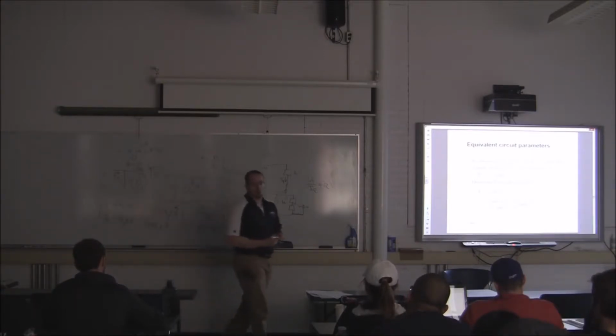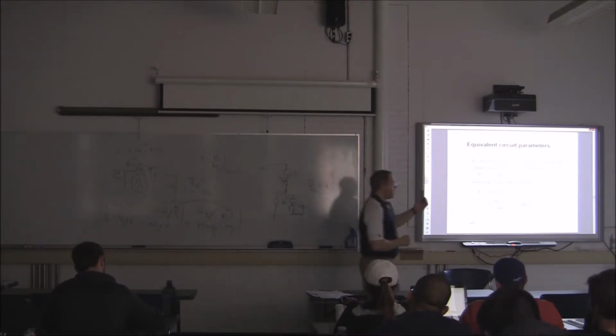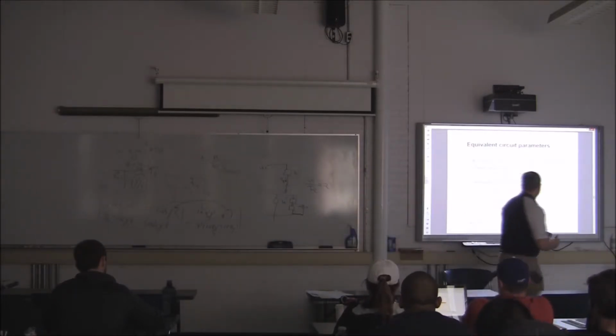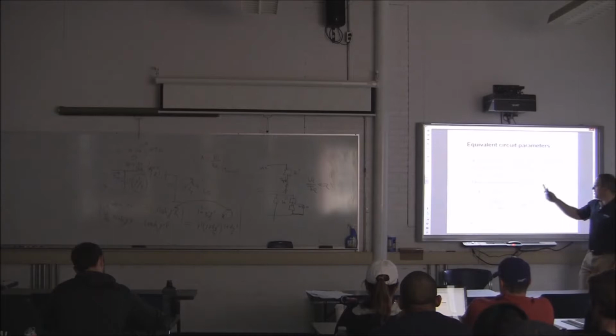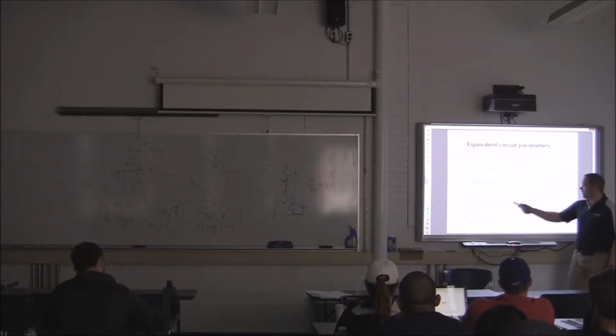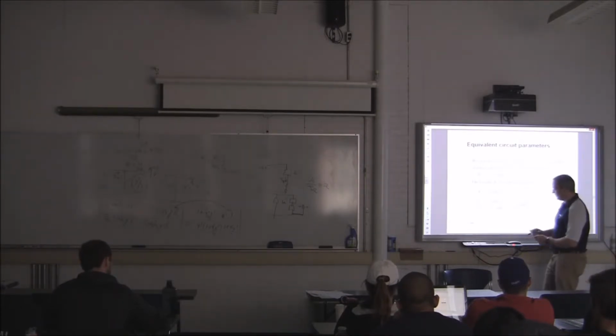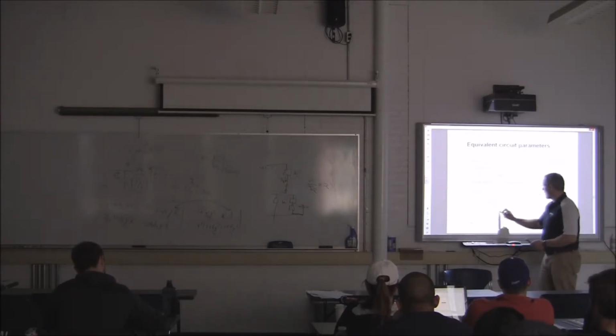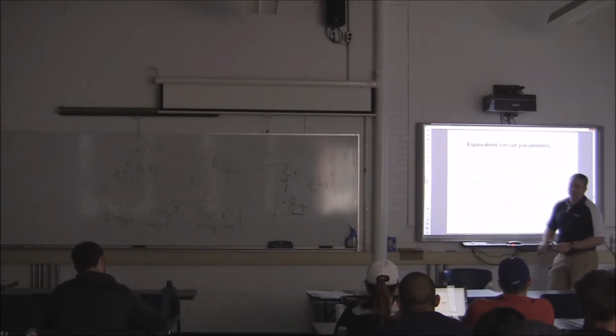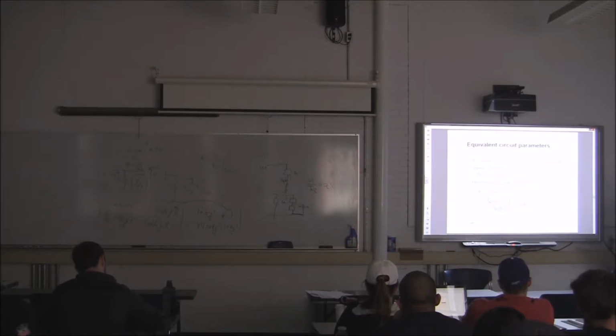Why would you solve for Y prime if you have to go back in and rewrite it and divide that by 2? So all I need to do is substitute. I solve for Y prime over 2, and I substitute in my Z prime, and I end up with 1 over Z sub C. And what I've done here is a hyperbolic trig identity, which tells you that it is the hyperbolic tangent of gamma L over 2. That's all that is.